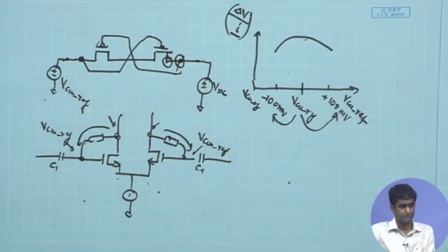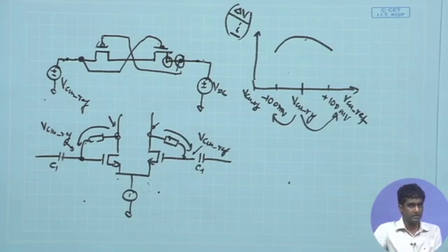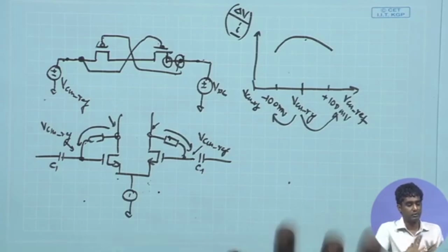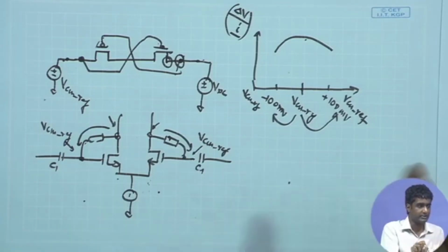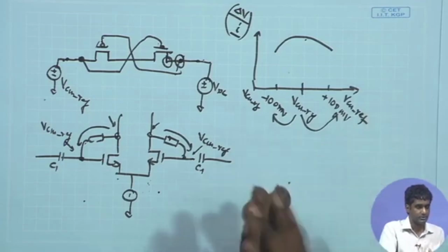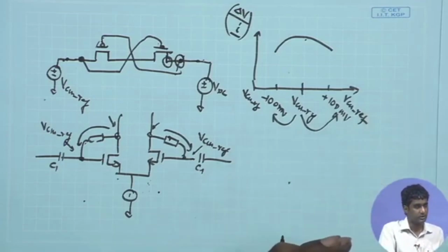So, how to initialize? By MOSFET switch, that is another way, but you have simulation options also there. We will check that in the LTSpice or even in Cadence. You have simulation options where you can apply initial conditions to some nodes. Even in the Spice simulation, generally, when you write codes for the Spice simulation, there also you can specify initial condition using the init statement. You can put some initial voltages at required points.